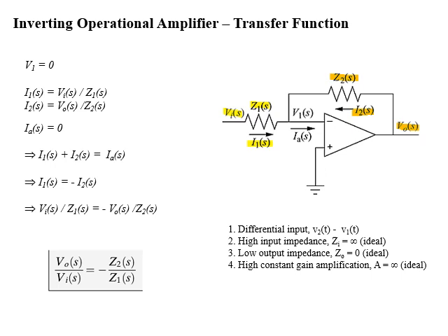Now we'll use the characteristic which states that op-amp has high input impedance, ideally equal to infinity. And we know that current always follows the path which has minimum impedance. So IA of s will be equal to 0, which implies that V1 of s is also equal to 0 as no current is flowing, so there is no potential difference.